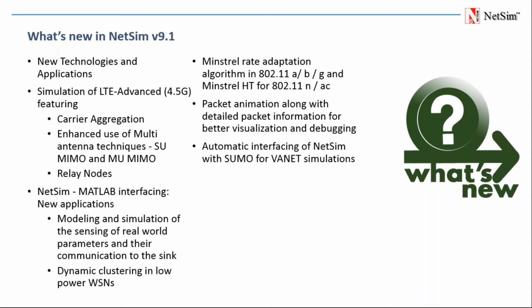NetSim recently launched version 9.1 in August. So some features have been added to the existing version. First is LTE advanced. It has been added with carrier aggregation and multi-antenna techniques such as SU MIMO and MU MIMO. Then relay nodes are there.